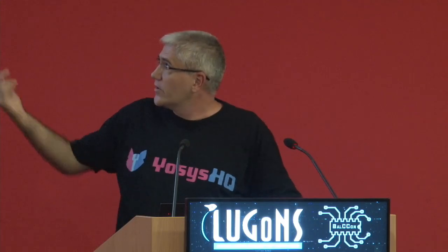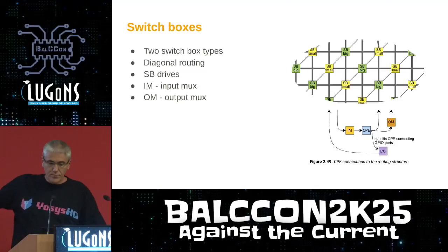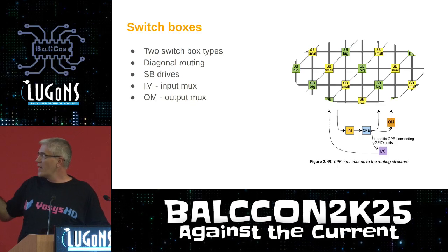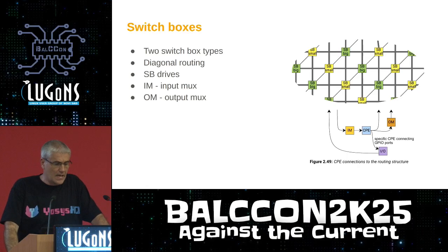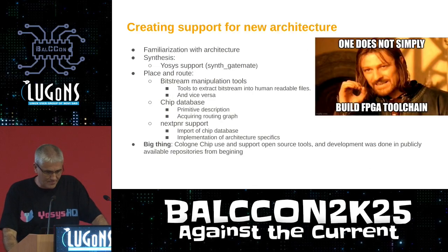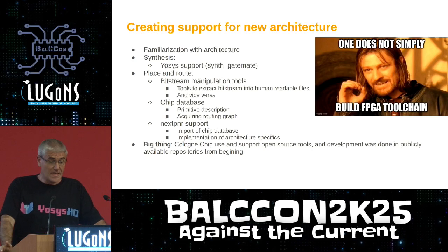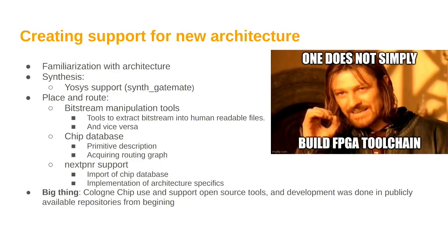As you may see on the image, all the inputs for the CPE block must come through the input mux, and they are feeding the output mux, but they can also feed the switch box. Like here, it's connected to the IOs. Every other non-CPE part is connected through the CPE, and you need to use the CPE to drive it.